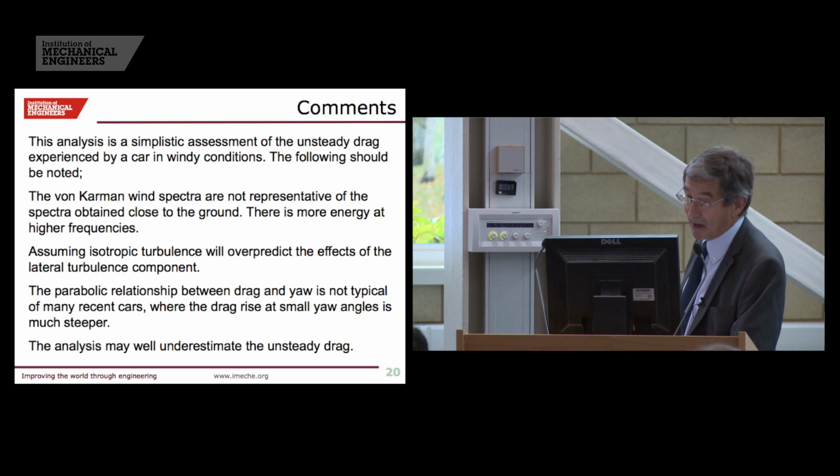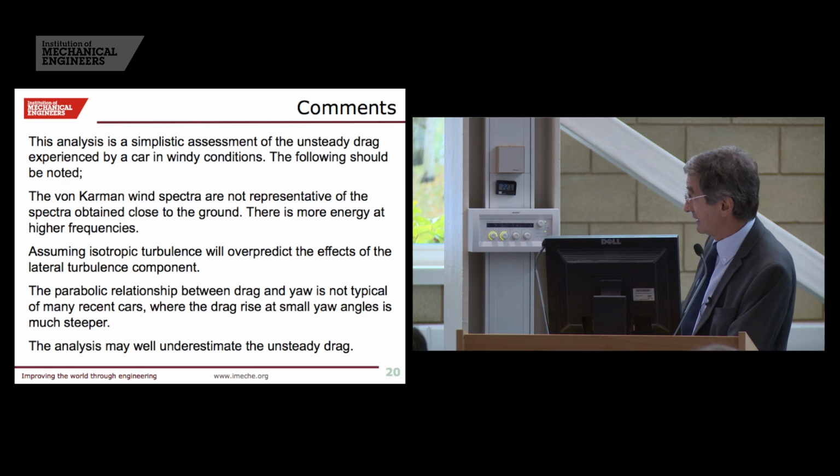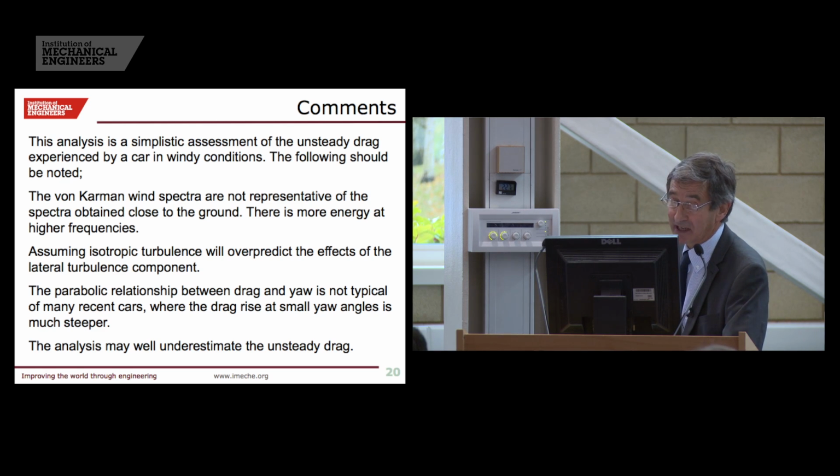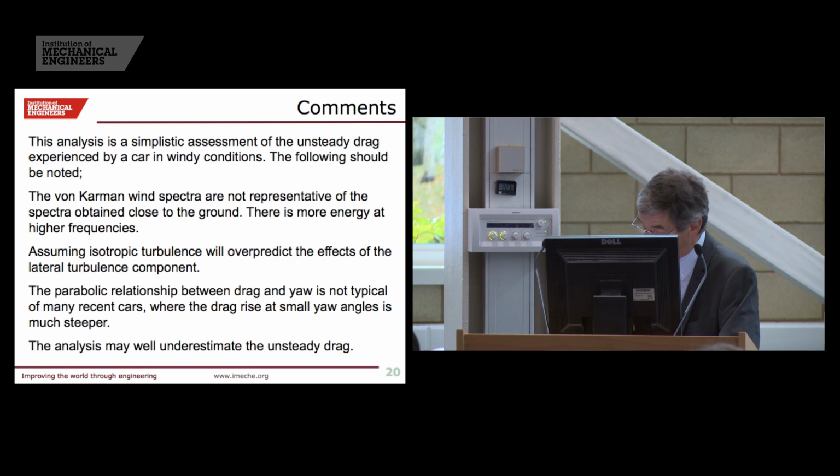Just a few comments. I've applied the von Karman spectra in this case, but that's not really fully representative of what happens very close to the ground, where there's more energy at lower frequencies. I've assumed isotropic turbulence because that's the easy thing to do, and this will tend to overpredict the effects of the lateral turbulence component, but that's smaller than the longitudinal one.